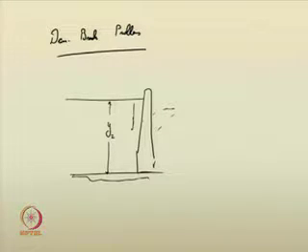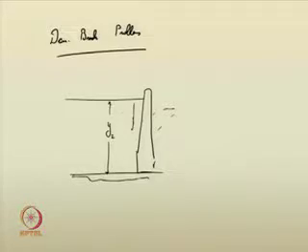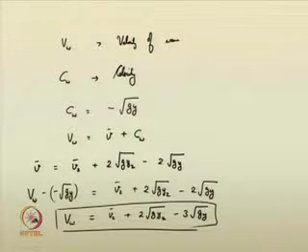A negative surge will be propagated to the upstream of the reservoir, as well as gushing of water occurring into the downstream. How this negative wave will affect the upstream of the reservoir due to dam break can be analyzed using this negative surge analysis. You know the known depth y2 here. So how severe is the wave, or how severe is the wave velocity? We have already studied the wave velocity Vw.